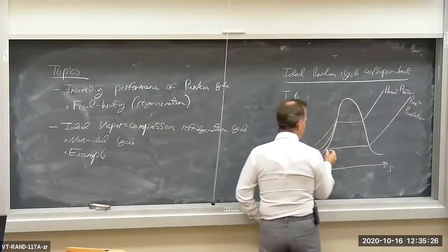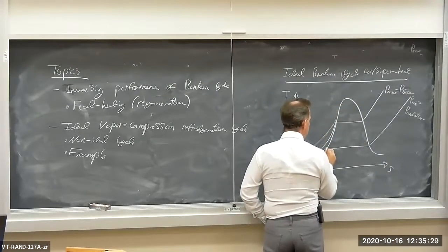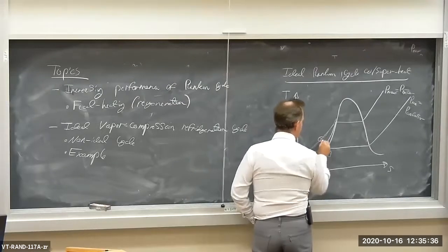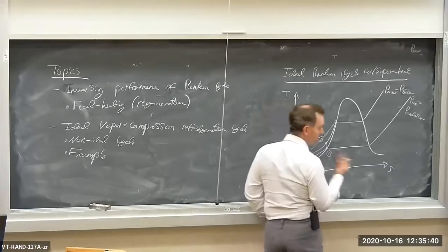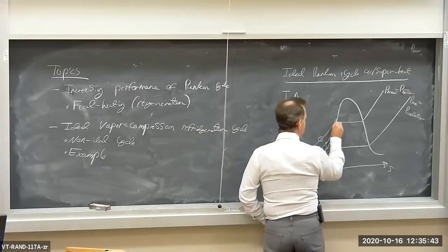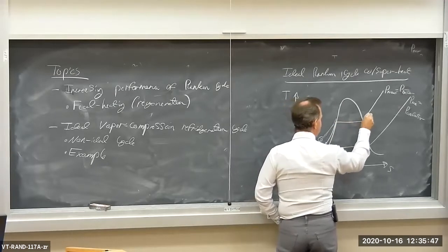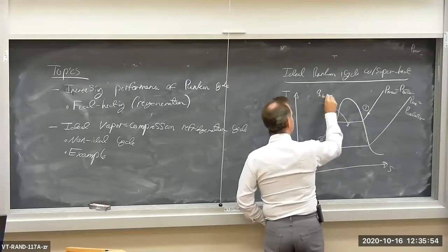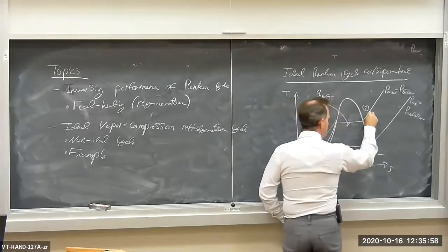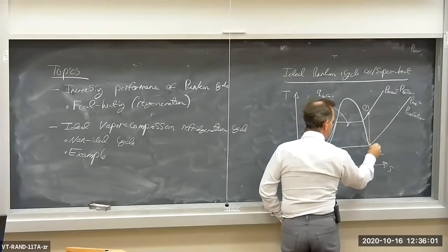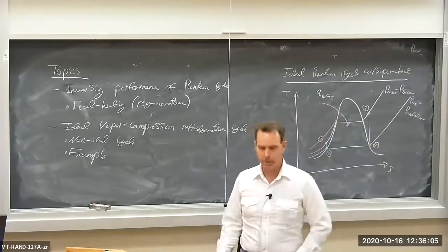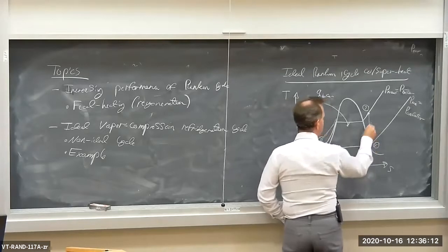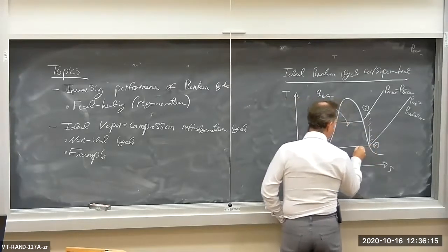So we start off with a saturated liquid, and then we isentropically compress, very small temperature change. It looks a little bit bigger than it does in real life here. Very small temperature change, but we go up to the P max isobar through a reversible pump. And then in the ideal cycle, we have constant pressure heat addition in the boiler up to some sort of superheated state at state 3. So this is our Q boiler. And then presumably we have an isentropic, because it's reversible and adiabatic, ideal expansion in the turbine. No heat transfer in the pump, no heat transfer in the turbine. And then we have heat rejection in the condenser.